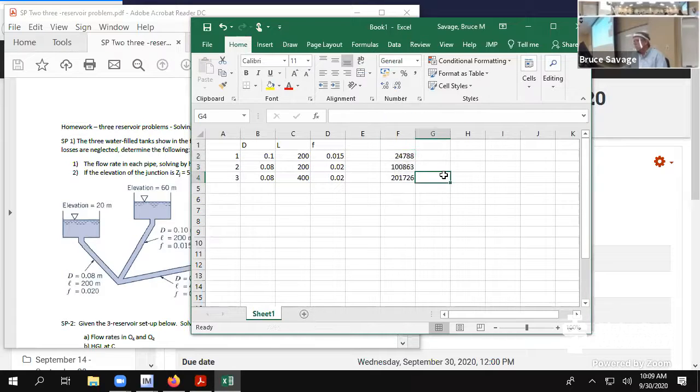Okay, so now these are awfully large, which is to be expected because, once again, in the metric system the standard unit is meters. Well, 1 meter is significantly larger than 1 foot. And when you square that with area, and you go ahead and calculate the flow rates, you're going to come up with some really, really small flow rates, and you're going to say that's essentially 0. Well, it is as long as you're talking about meters cubed per second. When you think about a meter, 3 feet by 3 feet by 3 feet, bring that back to the English system, it's a lot of water.